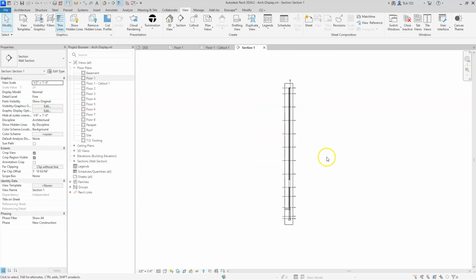Now, again, I'll just caution you that anytime you have a view that is relatively large, you are limited on the scale that you can use, and that limit is the size of the sheet that you've chosen. So if you are working on any project, it's always a good idea to decide on the sheet size very early in the project, because every sheet needs to be the same size. Remember, any architectural plan is intended to be stapled together in a book, and all the pages of a book must be the same size.